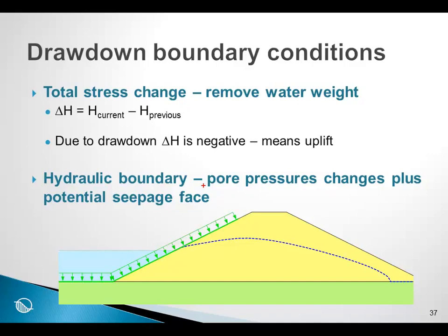Recall that we are doing a coupled analysis, so we have to say something about the SIGMA boundary conditions, or the stress-strain boundary conditions, but we also have to define the hydraulic boundary condition, and we have to define the pore pressure changes, which we will do through a function as the reservoir is being drawn down. But above the reservoir level, there could still be a seepage face, so we have to make sure that we tell SIGMA/W to check for the possibility of a seepage face.